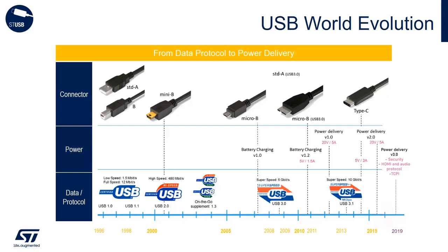The USB 3.0 specification was published in 2008 with the main goals of increasing the data rate up to 5 gigabit per second, decreasing power consumption while increasing power output available to the connected devices, and also maintaining backward compatibility with USB 2.0. USB 3.0 accomplished these goals by including a new higher speed bus called SuperSpeed, which maintains the slower data rate USB 2.0 bus in parallel. So if you examine a USB-C connector, you'll notice pins dedicated to the USB 2.0 signals, as well as two high-speed differential lanes on separate pins.